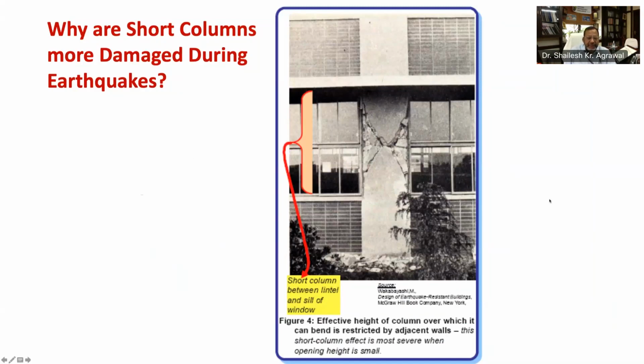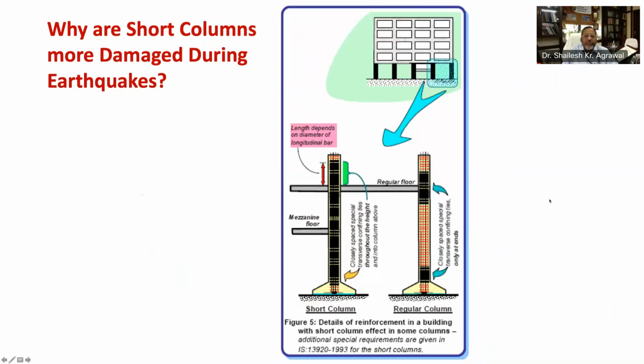Let's understand that. In a new building, short columns should be avoided to the extent possible during architectural design itself. When it is not possible to avoid short columns, this effect must be addressed in structural design. The Ductile Detailing Code, that is IS 13920, stipulates special confining reinforcement to be provided over the full length of columns that are likely to sustain short column effect.